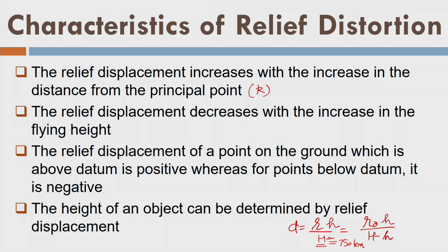That means I want to do the XY mapping, not the 3D mapping, right? And that's the idea here. Why do we prefer aerial photography or aerial photogrammetry compared to satellite photogrammetry? Satellite photogrammetry will give me minimum vertical exaggeration, or vertical distance measurement is hardly possible, and as a result I cannot create reliable 3D information maps using satellite photogrammetry.